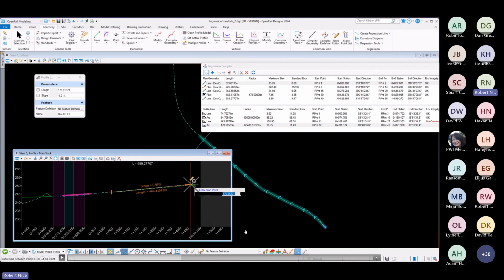You see on the end of that cursor there, I talked about on the InRoads part, these new little icons for snaps. So this is part of them. That ruler means there's a civil rule being applied. So if you just see a normal little cross, I can't remember what the MicroStation snaps were, that'd just be MicroStation, but this means it's going to be a civil rule applied. When you see those, you know there's a civil rule being applied to any of your geometry.